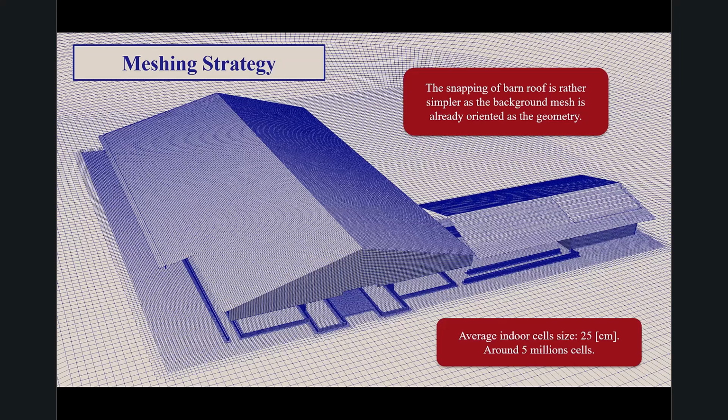Yeah. Well, we did have quite a lot of problems related to the instability. So we have adopted quite a small time step in order to have numerical stability. We are working with a time step of 0.01 seconds, because we have lots of higher speeds and lots of gradients and quite large cells. So the simulation stability is quite a problem.